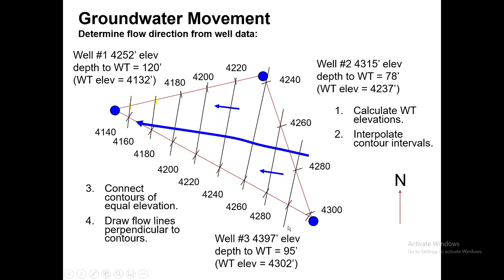We can easily make the contours based on the same levels of elevation. So for example, this is one of the same level of elevation, 4280 elevation, and this is 4280 elevation on this line, 4260 elevation on this, and 4260 on this line, and then 4240 and 4240. This is the point here, and for this line, this is the point. Same, this is the point here, and this is the same point here. We will be joining these points. So we are having these straight lines which are joining the same elevation levels.